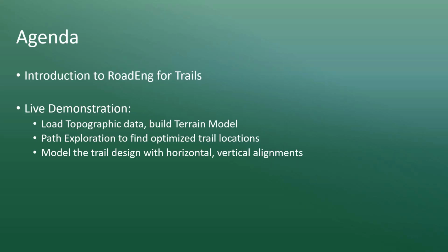And then we will switch into location to model the trail corridor. In location, we will show you how to adjust cross-section geometries, optimize our vertical alignment, and make micro adjustments manually to the design to ensure the trail is well suited to our project needs.